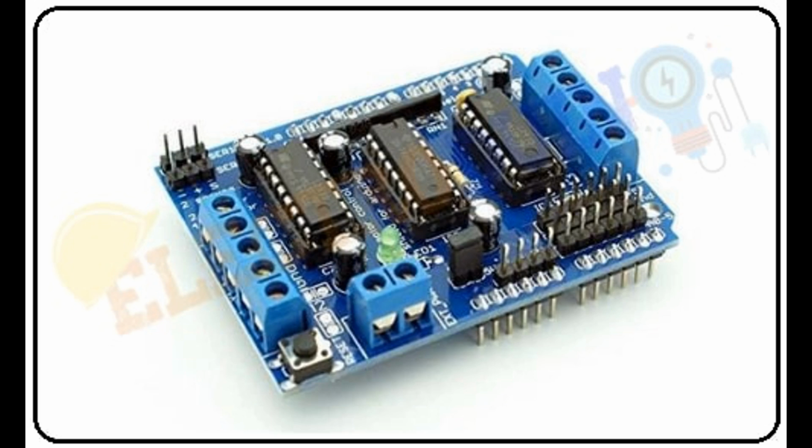3. Types of AC motor drivers, VFDs. A. Volts per hertz, V/F control. Function. V/F control is a basic method of controlling AC motor speed in VFDs. The voltage is adjusted in proportion to the frequency to maintain a constant ratio, which ensures that the motor operates within safe limits. Operation. As the frequency increases, the voltage is also increased to maintain the magnetic field strength in the motor. This simple method is typically used for applications where precision and speed control are not critical.